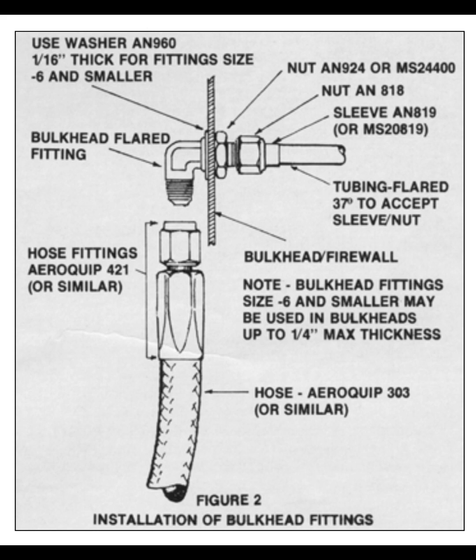What type of rubber is used in flexible lines that carry phosphate ester hydraulic fluid? Synthetic. What type of information is on a hose lay line? Type of hose, quarter and year of manufacture.